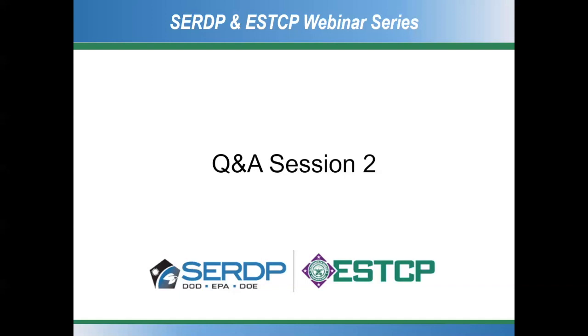So in terms of surprising, I mentioned a couple about the phase mattering and about the role of the oil content. One thing we didn't talk about, but I know a number of groups are seeing, I know when I was at Lehigh, and then the people at Purdue, and then all of us, is the role of spontaneous emulsification. It's not just about agitating these emulsions and that they form oil droplets, but that if there's any sort of oil-water interface, you can actually have oil droplets that spontaneously form near that interface and produce a non-trivial amount of oil that goes into the cream in the emulsion phase. So that's just been very interesting to look at, and that's emerged as a part of this work.